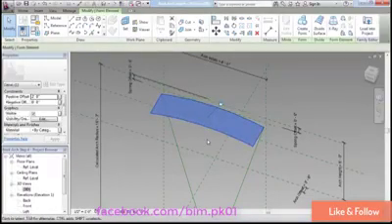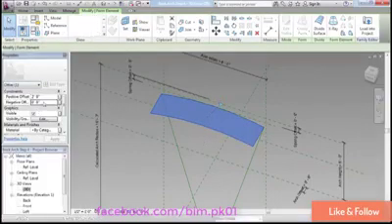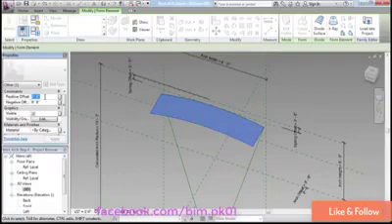Now when I click on this form element, over here on the Properties palette, it has a negative offset and a positive offset. For this example, I'm going to dial in explicit numbers and just assume that my bricks are 8 inches deep. But notice that there are the little buttons over here. So we certainly could link these up with parameters, but I think by now you've maybe had your fill of parameters for the time being.